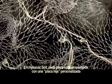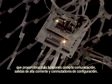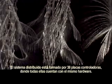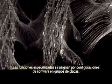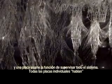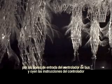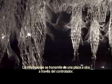In Hylozoic Soil, each board is paired with a custom daughter board that provides extended functions, including communication, high current outputs, and configuration switches. The distributed system consists of 38 controller boards, all with identical hardware. Specialized functions are assigned by software setups in groups of boards, and one board assumes a supervisory role for the entire system. Individual boards all talk on the bus controller's receive line and listen to the controller's instructions on the parallel send lines. Information is transferred from board to board via the controller.